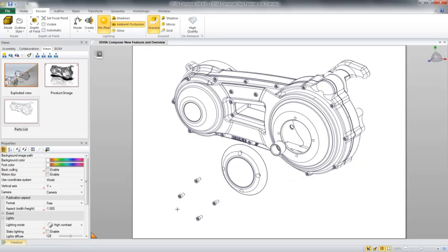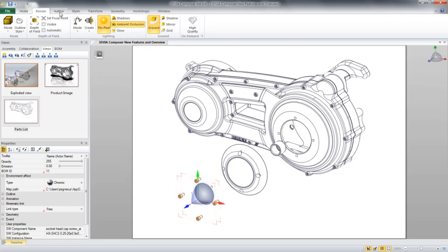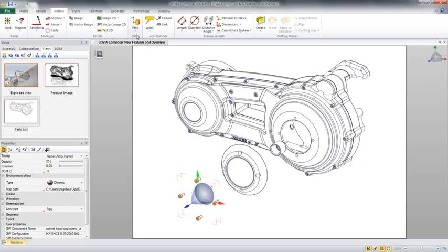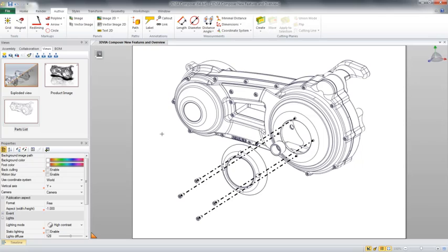To show how these fasteners go into place, we might want to add some trail lines. This is where the authoring tools in 3D Via Composer come in. The associative and non-associative paths are a great way to quickly and easily create trail lines on our design. However, as you can see, they appear over our geometry in some cases, and they don't necessarily match our styles.